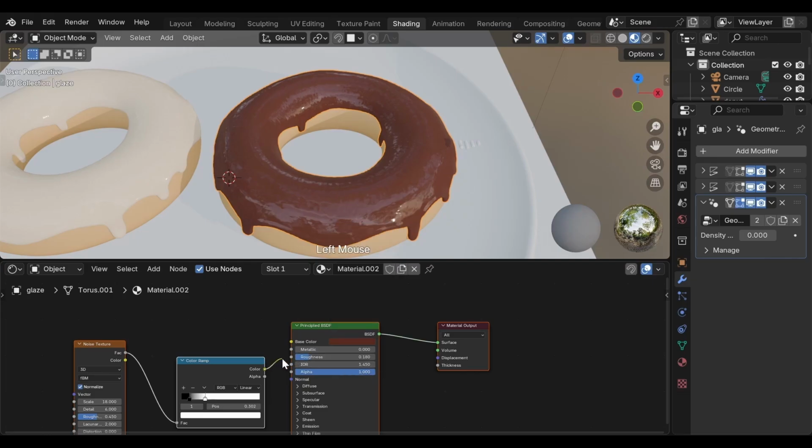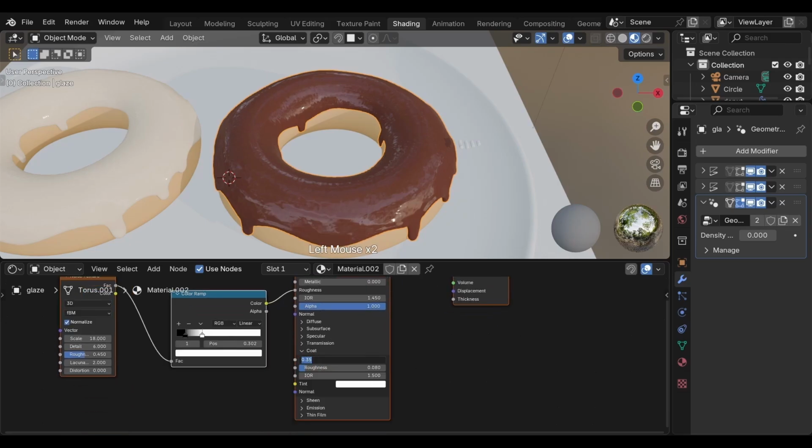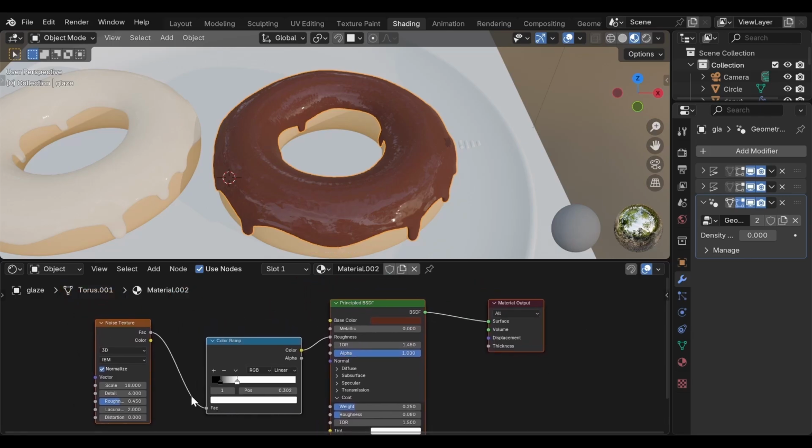Next, adjust roughness. Set it to around 0.22. That keeps the surface glossy, but slightly more controlled than the sugar glaze. Now lower the clear coat value to about 0.25. Sugar glaze reflects light strongly at the surface. Chocolate behaves differently. Chocolate absorbs more light. So instead of relying on heavy surface shine, we let lighting contrast define the form. Darker materials depend more on lighting direction and intensity, and once we introduce proper sunlight, this will respond nicely.